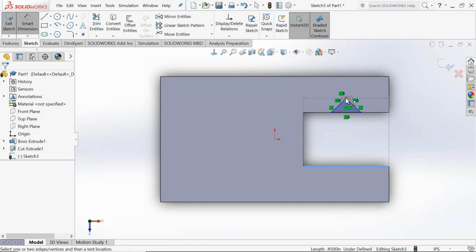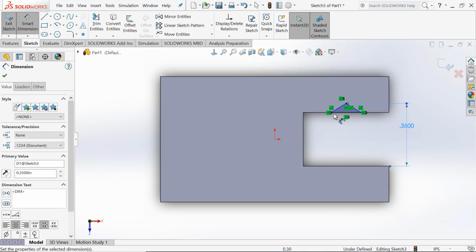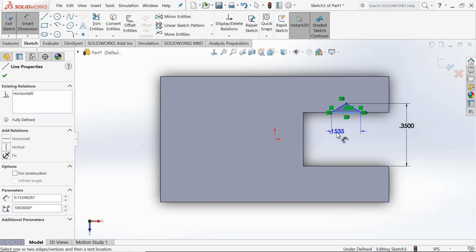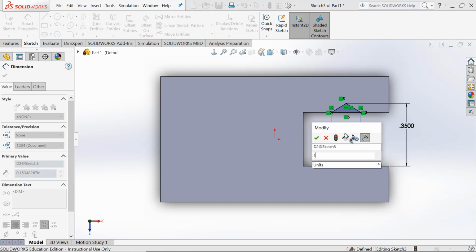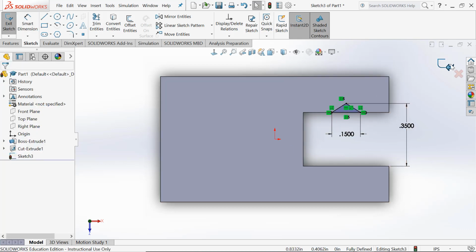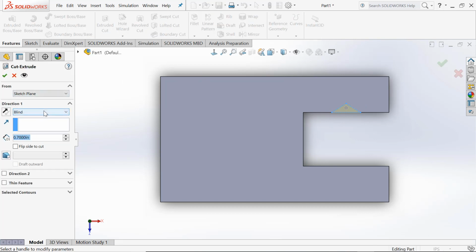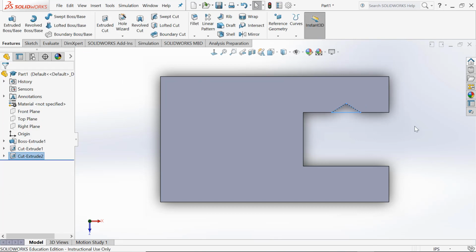From here to there, it probably gives you that number. I'm not sure. I don't remember what it is. And then it might give you the length of this line here. It might be something like that. So those two, again, very clear dimensions that you could measure if you had the part in front of you, are all you need to define and locate that. It's a fully defined thing. And again, you would do extruded cut and through all.